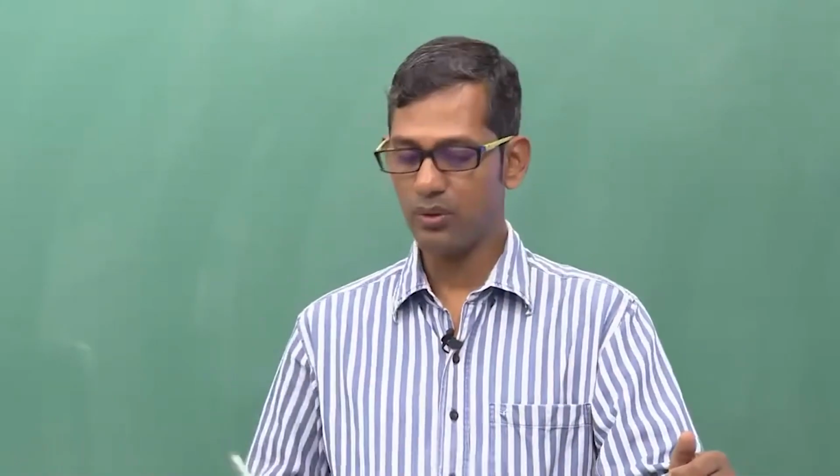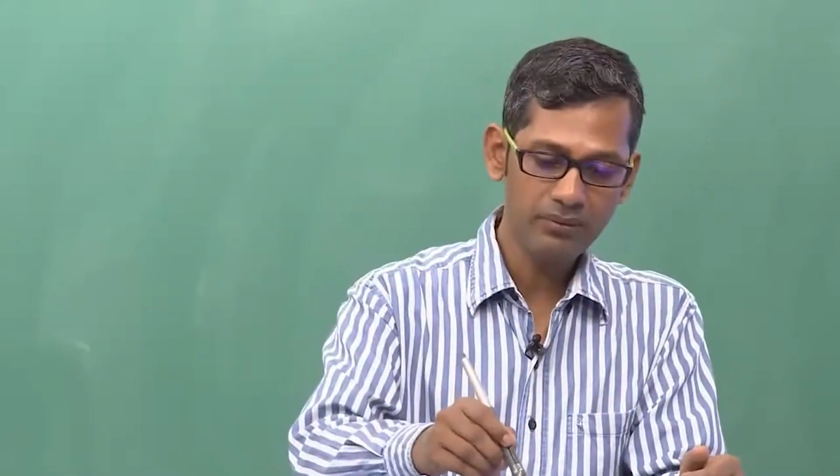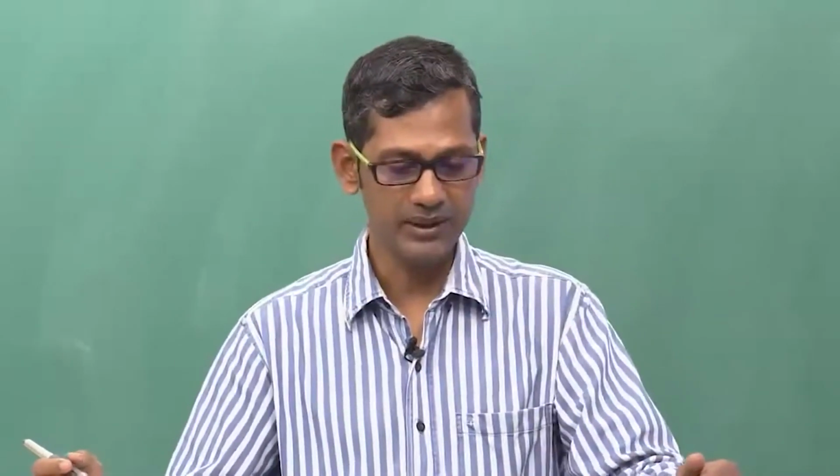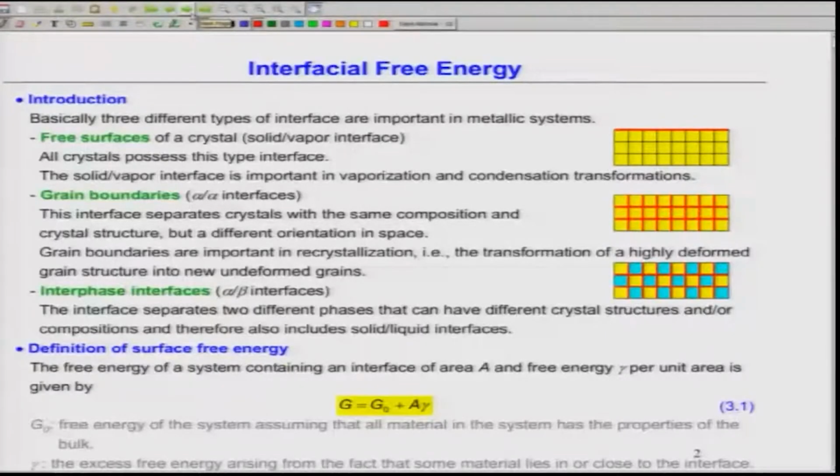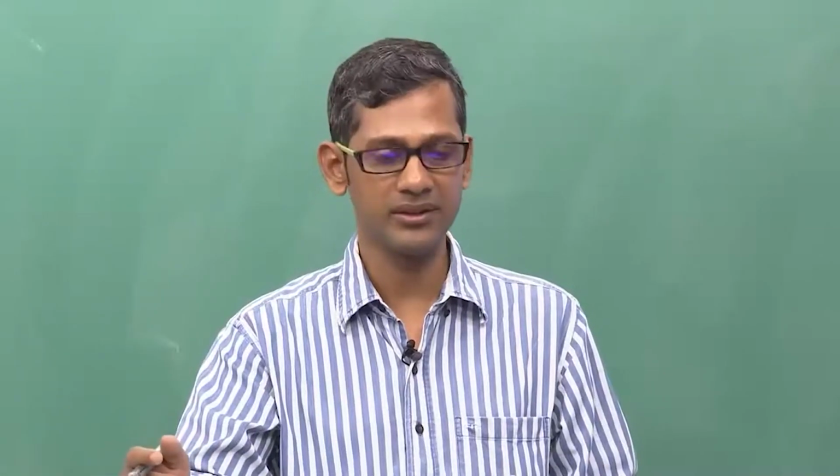So let us first look into the meaning of interfacial free energy. By the way, before I move on, there are 3 types of interfaces which are important. One, as I told you, is the free interface, that is the vapor, and the other 2 are either the interface between the same phase, between grains, or the interface between two phases.